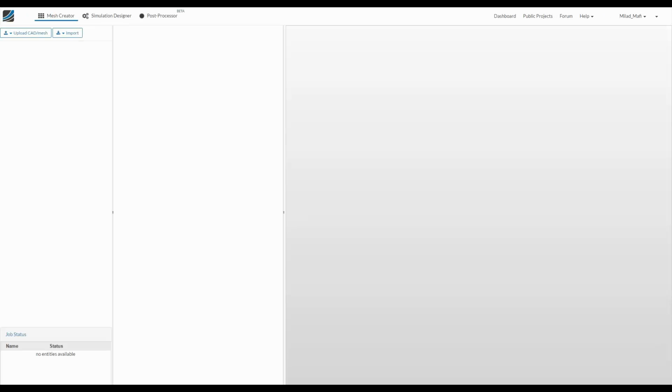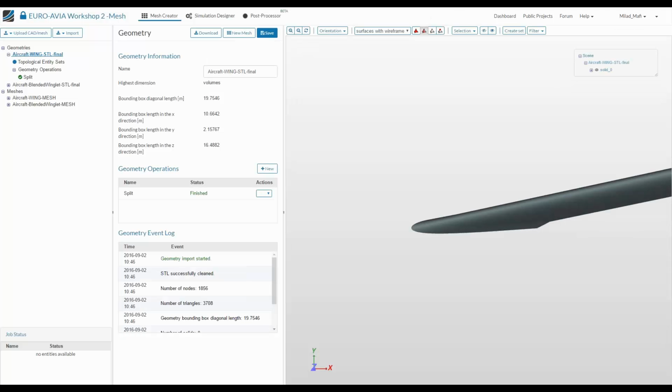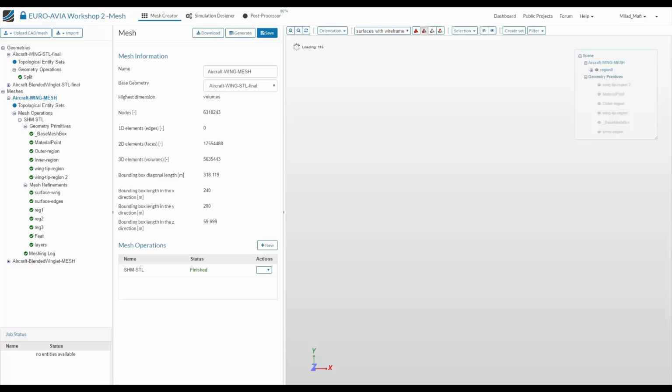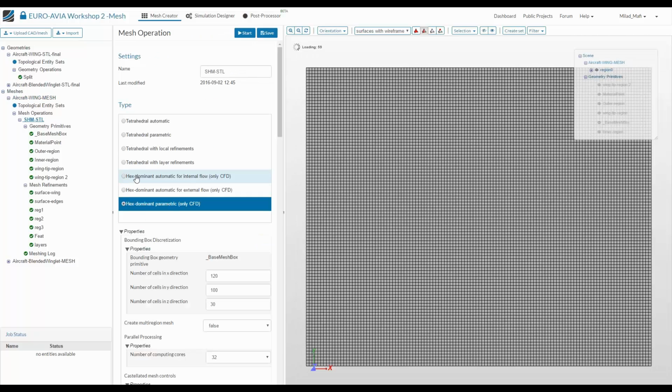By the way, there's a question by Mark again. He wants to know if it's possible to do a smart meshing which would automatically adapt to the shape of the studied object. Yes, this is possible. We even have this kind of mesh available, and this mesh, let me just show it to you, is called the hex dominant automatic mesh. But for sure the result is not as good as when you do it manually, but for a lot of applications it's enough. And we're also working on some very nice features which will automate meshing, even parametric meshing, more and more in the future.